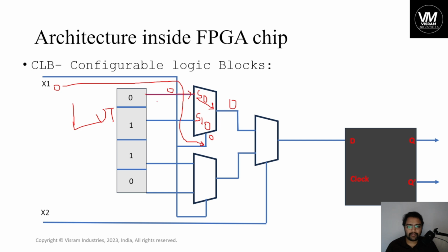So now the data is 0 here and the output is 0. So in the same way, if we have 0, right? 0 is the selection port. So here the 0, and here it is S0, and here it is S1. So what is the data to be selected? Which port is enabled now? This selection port is enabled. So hence data is 1 here. So this one is pushed forward here as the output as 1. So now 0 and 1.